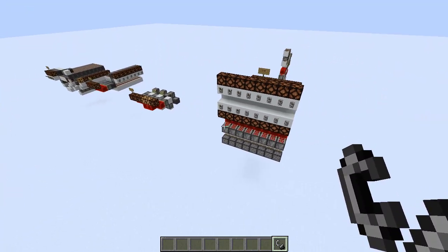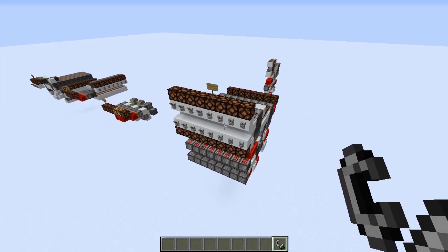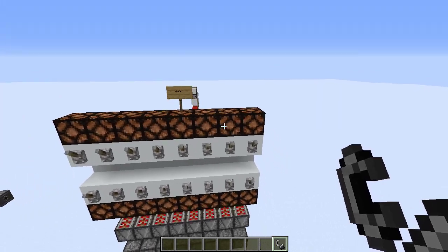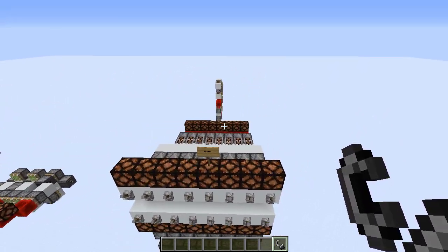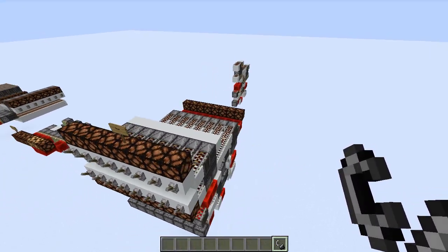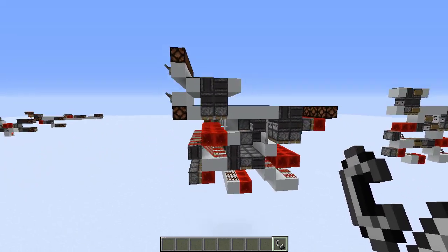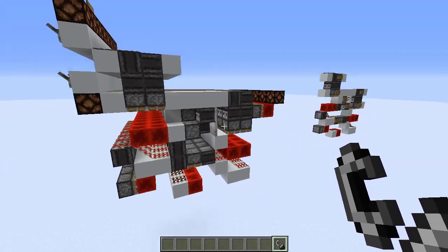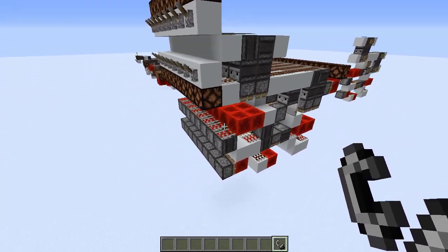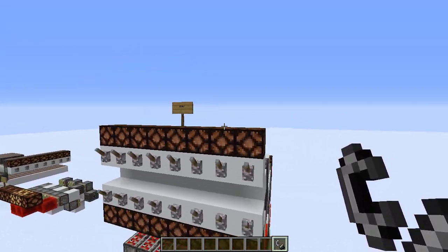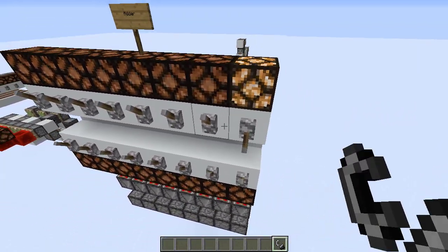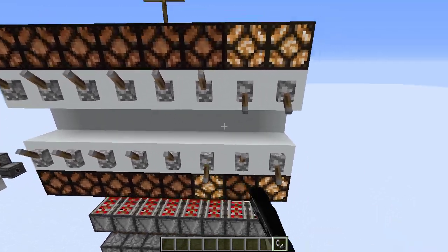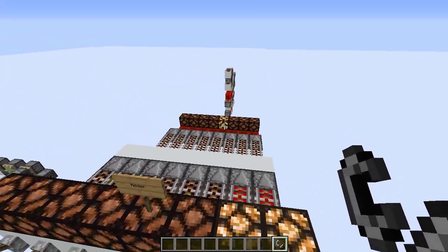Alright, now this is all just some easy logic stuff. So I decided to make something a bit more complicated using this, just to show that this actually has applications. This is a complete 8-bit adder. I don't want to say this is the most compact one ever made, because it probably isn't, but it's pretty darn compact. It's 10 by 10 by 1 per bit. So let's try it. So 3, we get 3 on the output. Then if I do 5, there we go, we get 8.